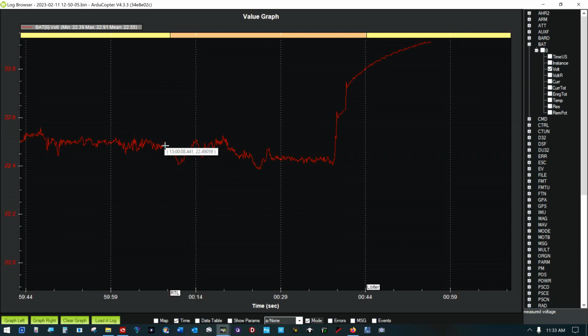That's 1 o'clock, 8 seconds after 1 o'clock. See, that's 18 seconds right in here. I suspect it did do a battery failsafe right here, and that's what that color's for, and right here's the reason I suspect that. It finally got below 22.5 volts for 10 seconds duration right here, in my humble opinion.